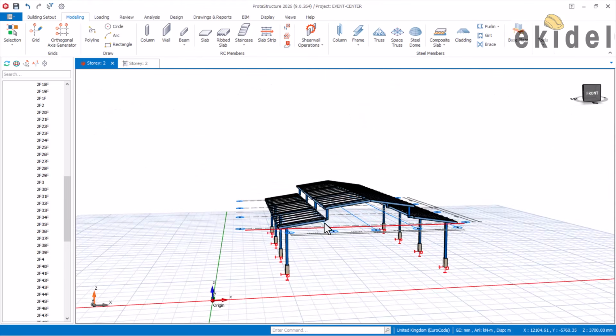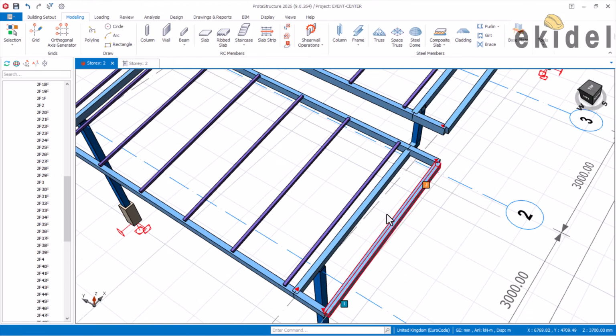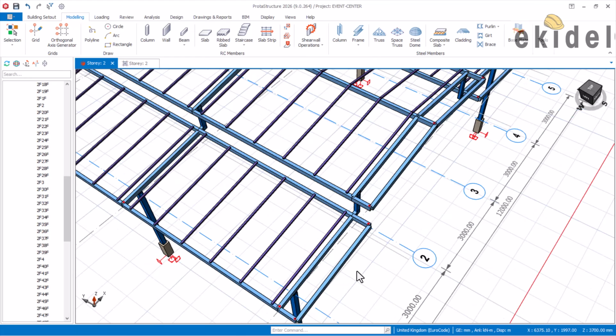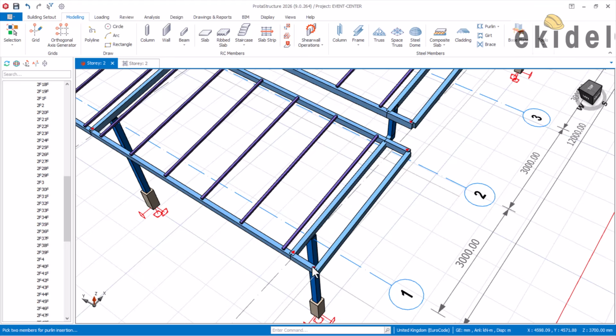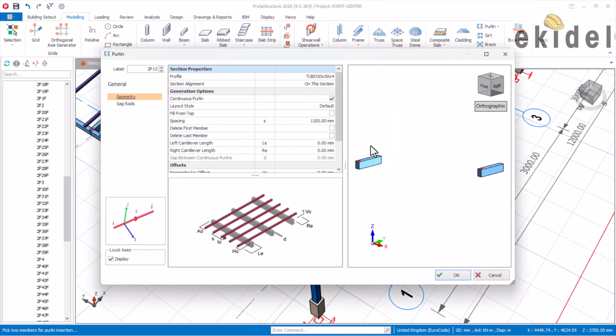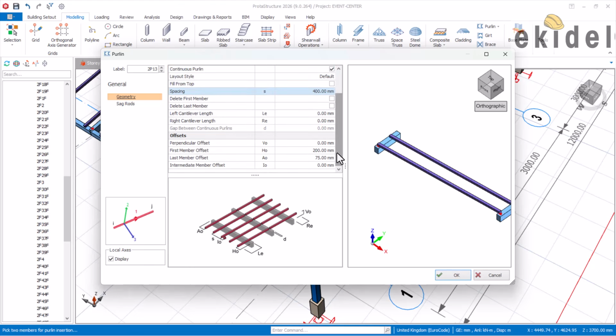So once I've added all these polylines now, we then move to the next phase, which is adding the smaller ones here, which will have a different setting of polyline. For this other one, we come now, click on this place here again, polylines again. I'll click on this to this. And this appears, but I guess it's not showing because the spacing is too much. Come here, I'll use 400 in this case for this design. Come here now, I'll remove this now to be 0. Again, I'll come here, it will be 100 millimeter, and then say okay for this.